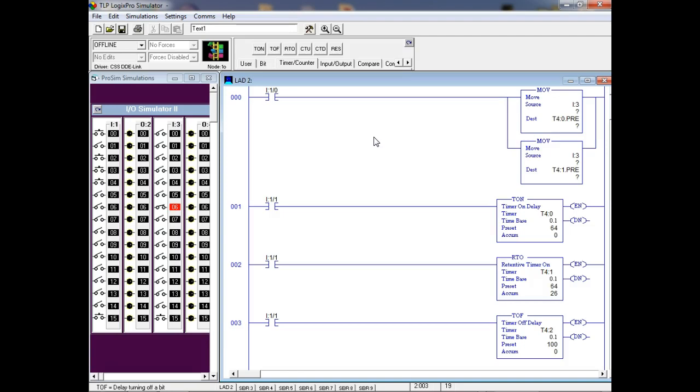We don't use Karnaugh maps at all. I hate Karnaugh maps. Well, Karnaugh maps are neat as long as you don't get above 4 inputs, because it's a square. If you use 4 inputs, that's 16 blocks right off the bat. If you have 5 inputs, that's 32 blocks in your Karnaugh map. If you add another input, that's 64 blocks, right? You understand? So a Karnaugh map is about as useless as truth tables.